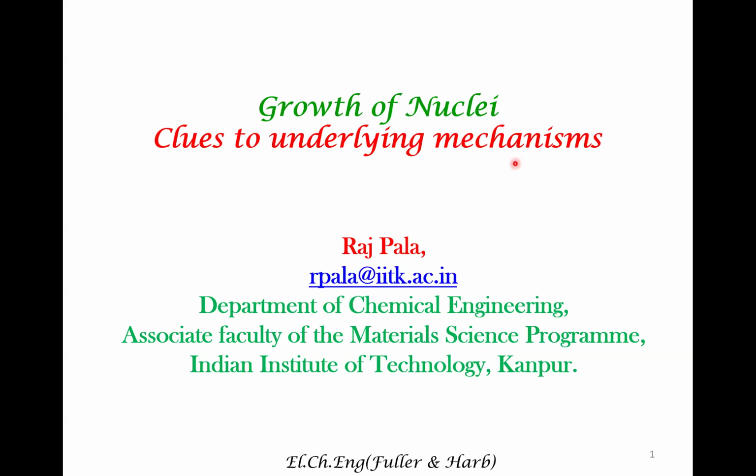Welcome back. In this lecture, we will look at certain aspects of electrodeposition, especially certain mechanisms that are associated with growth following nucleation. So the phenomena is fairly complex for multiple reasons. Crystal growth has been studied from the time of Ostwald. There have been beautiful experiments. And in the initial stages, well, experiments were done.